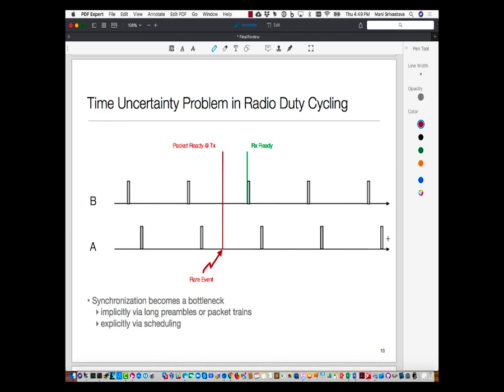And a common way that we shut radios down: in the case of processors, the shutdown wake up strategy is basically go to sleep, interrupt comes, wake up. Whether you pre-wake up or wake up upon receiving the events, they have different trade-offs, but that's the basic strategy. With radios, what's commonly done is that we duty cycle the radio. So essentially, the radio once in a while wakes up, listens, is there anything for me? If not, goes back to sleep and repeats the process.